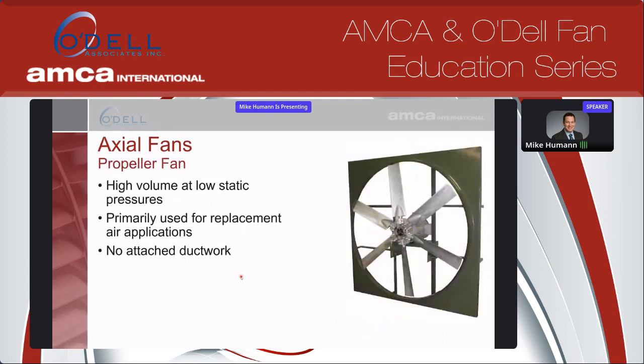A couple of those different fans, you have a propeller fan. This is used for a lot of replacement air applications, just general ventilation, typically no ductwork attached. Again, following the axial fan, it's a high volume at a very low static pressure. Any differences in static pressure can certainly reduce the volume because these only produce a couple inches of pressure.